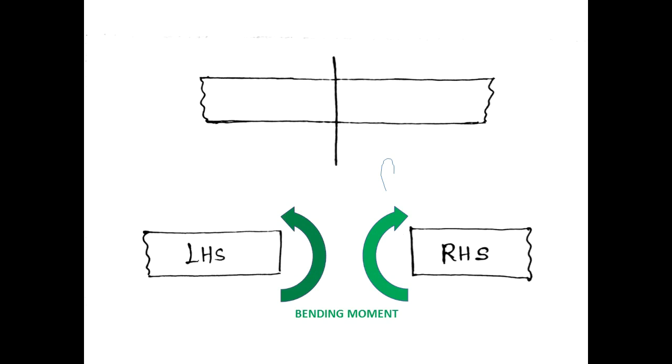This is the bending moment. Bending moment acts perpendicular to the cutting surface. Most US books consider anticlockwise moment positive for the LHS and clockwise moment positive for the RHS portion, or, as commonly said for both LHS and RHS, sagging moment is positive. This term is discussed later.